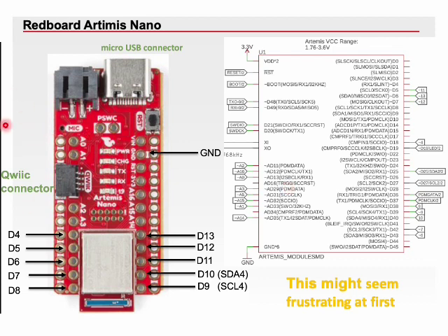The Qwiic connector is a type of I2C compatible connector used in Sparkfun electronics products. It consists of 4 pins with power, ground, and 2 I2C communication lines.